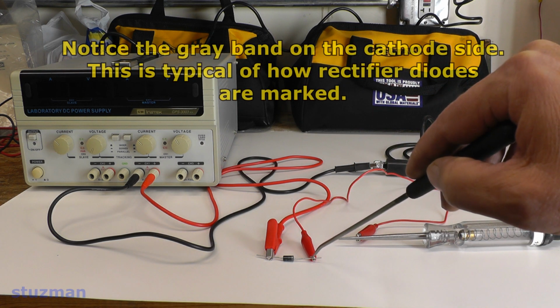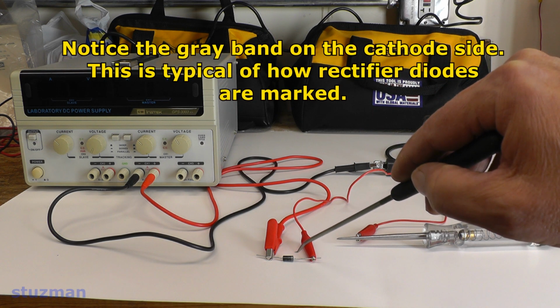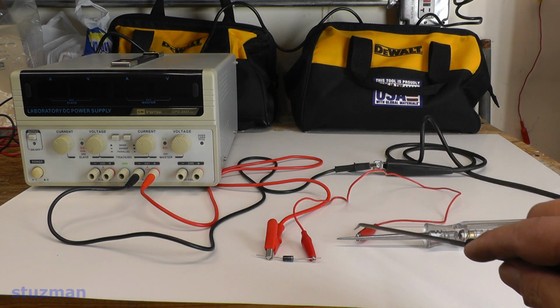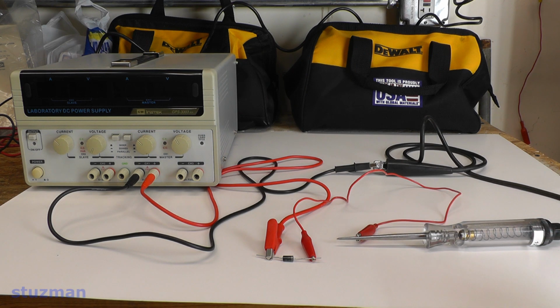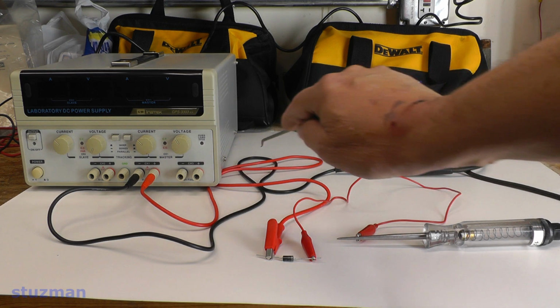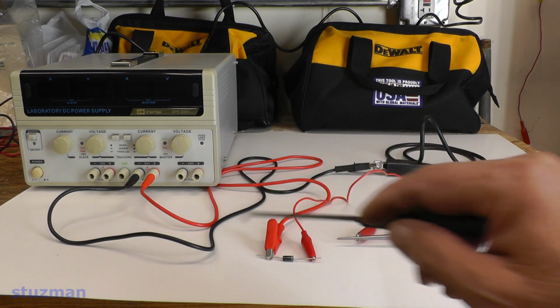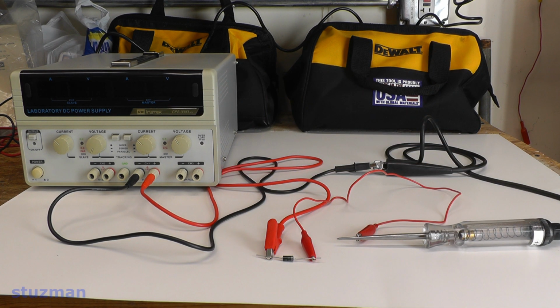Then over here on the other side, the cathode, which has the band, is going to go to one side of the test light. Coming off the other side of the test light, we go right straight back, and we follow the black wire right back to the negative side of the DC power supply. So basically this diode is wired in series with the test light.